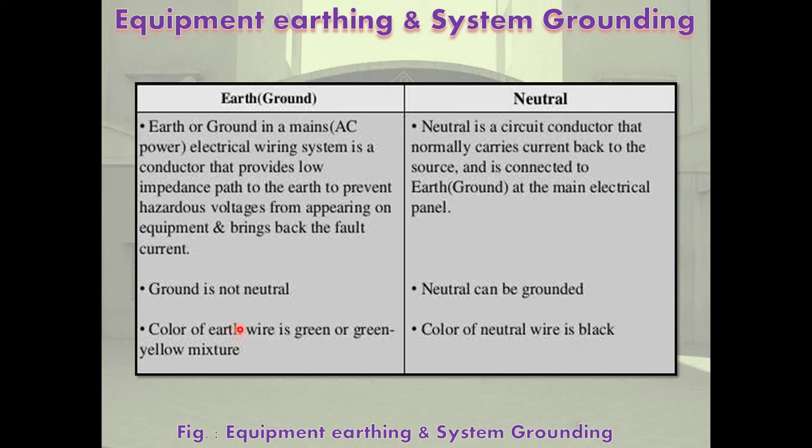Equipment earthing refers to the earthing of non-current carrying parts such as motor body, switchgear enclosure, transformer tanks, conduit, support structure, towers, poles, cable sheath, body of portable equipment, earth terminals of surge arresters and earthing switches. Neutral earthing is different from equipment earthing. Neutral earthing refers to connecting to ground the neutral point of a star connected winding.